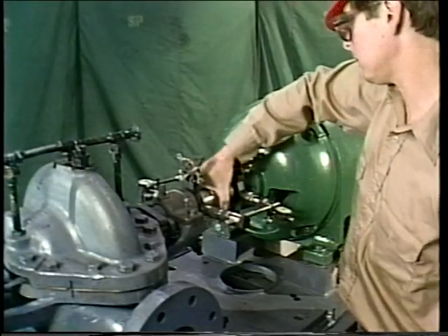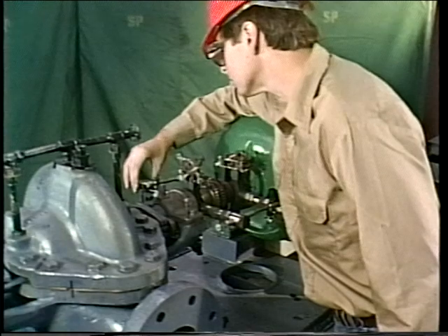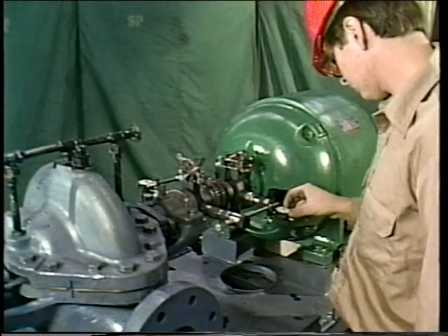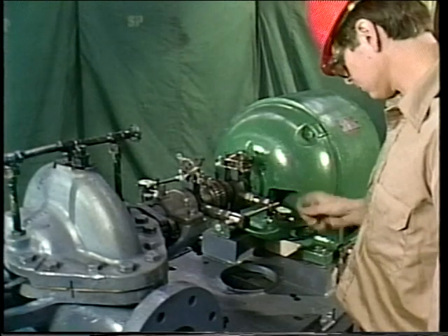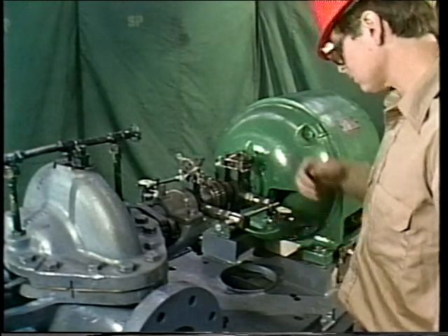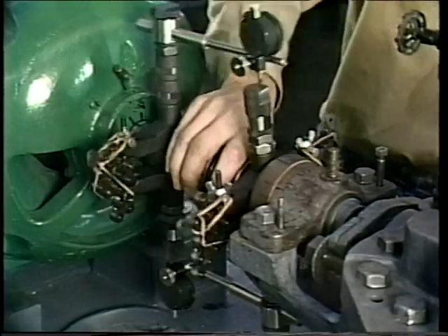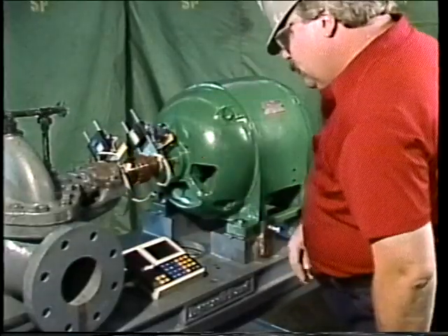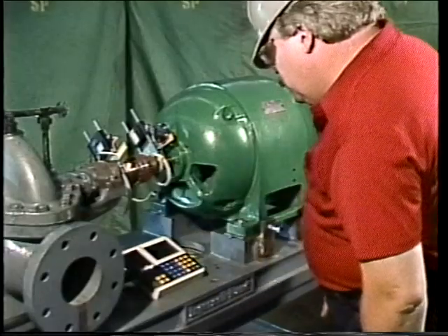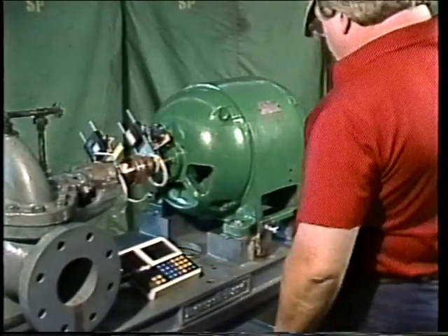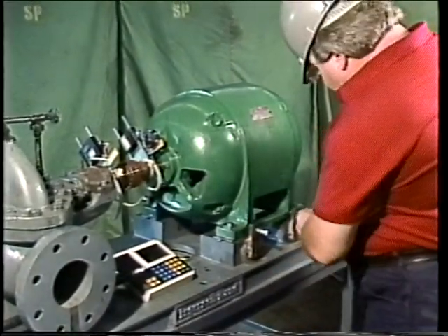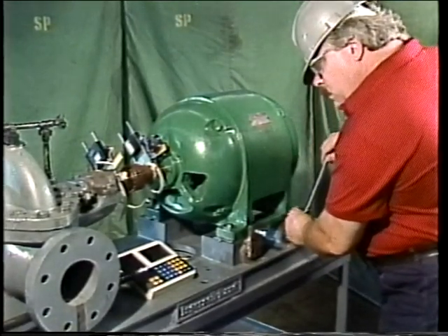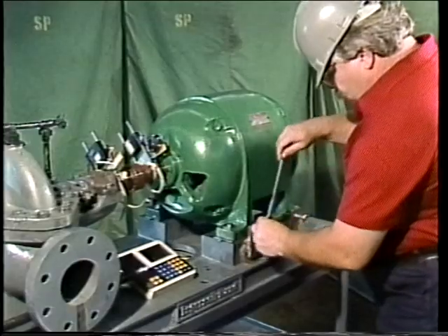Another common cause of vibration in rotating machinery is shaft misalignment. A small amount of misalignment between shafts can put additional stresses on the shaft and its bearings. These additional stresses produce their own distinct vibration. Vibration caused by misalignment can occur even when flexible couplings and self-aligning bearings are used. The only way to correct this condition is to align the shafts until they're within the manufacturer's specifications.